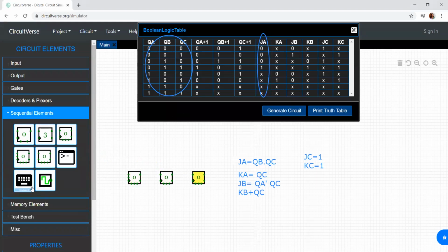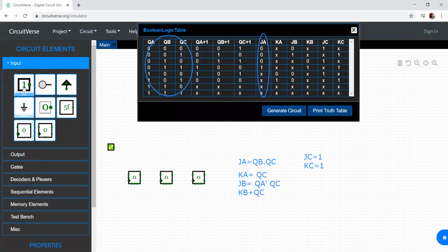Now the clock. Actually clock should be given using a clock pulse, but I want to visualize the output, so I'll give the clock using this. Actually the clock is a sequential element like a pulse. As of now, we are going to give the clock from this one to visualize the output. All flip-flops are clocked simultaneously. Since it's a synchronous circuit, I can give the same clock. Synchronous mod 6 counter is what we are designing.